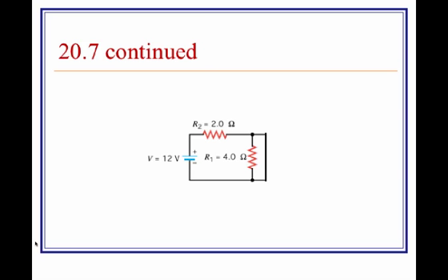because that will make the equivalent resistance of that branch zero. So here we have the 4 and the 0 and the short circuit on the end. It will make the equivalent resistance 0. The total resistance, once you add this together along with the other resistor here, the 2 ohm resistor, means that the equivalent resistance of this circuit is 2.